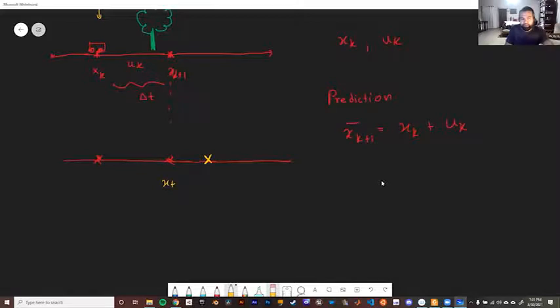So this is the actual xk plus. What I've drawn in red is where it should be, but our prediction, because of the noise in the encoder and all that stuff, assumes that we're here. So this is xk, this is xk plus. Cool. So there's a small error here, you can see, right? And again, I'll actually draw the Gaussian here as well, right? So there'll be some sort of Gaussian here like this.